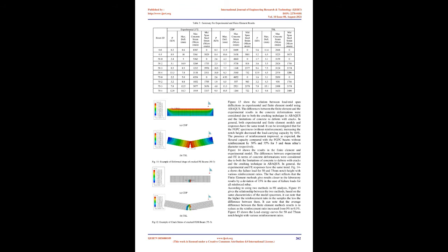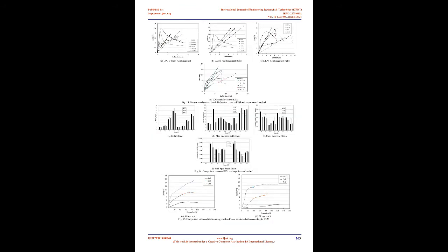The CDP requires concrete tensile and compressive constitutive relationships, crushing and cracking damage parameters, and special parameters such as dilation angle, eccentricity, biaxial loading ratio, the coefficient K and viscosity parameter. These parameters can be assigned their commonly used values in Table 2.